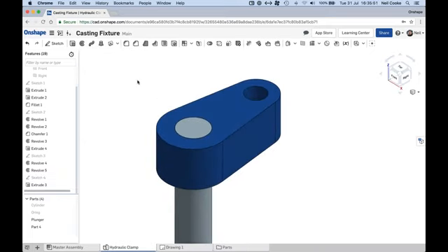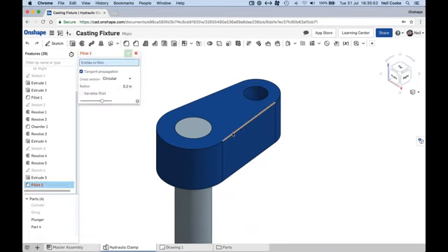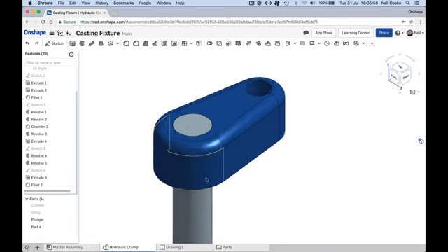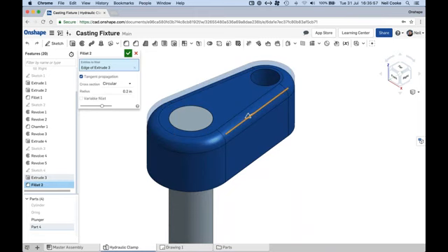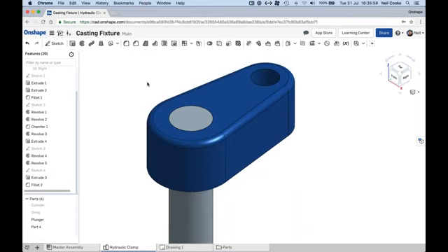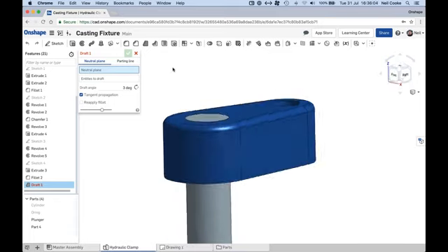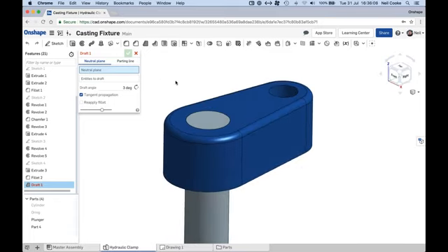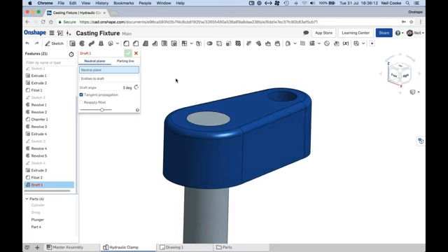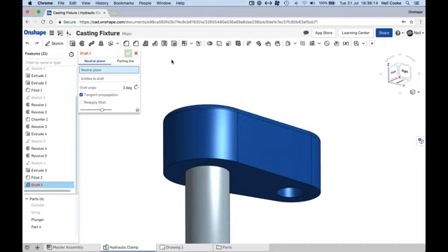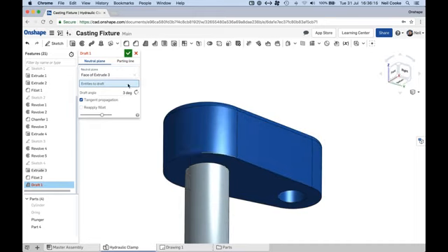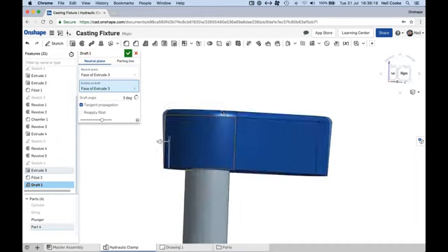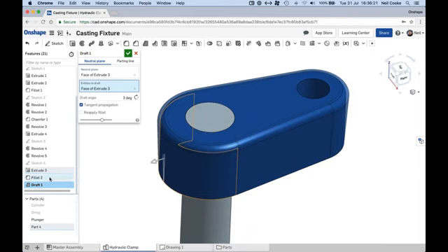You can also do things like, let's just add a fillet on there, for example. Let me just make that a little bit smaller. Okay, and just things like if you're adding draft. I know they introduced this recently in Creo 5. So if you're using Creo 5, then you're going to be used to this. But the sort of thing you can't do in SolidWorks is if you're creating a draft on here and you want to draft all these edges, you can see that it doesn't matter that the draft came after the fillet.